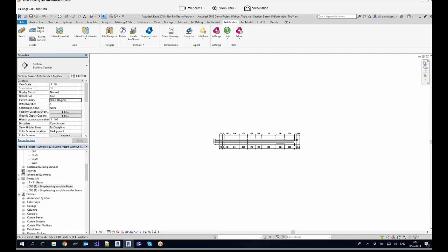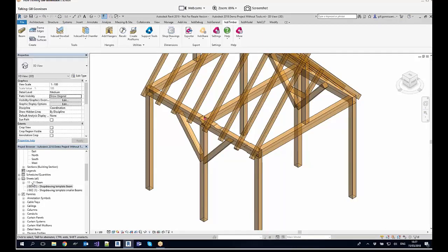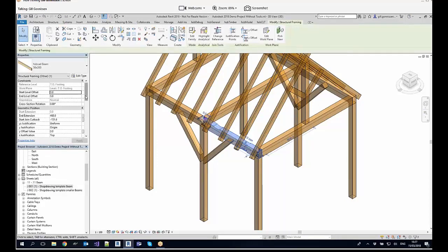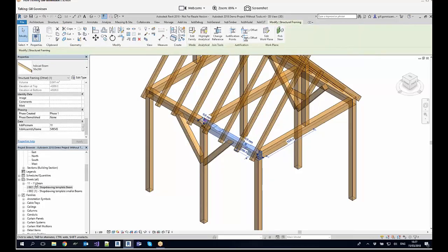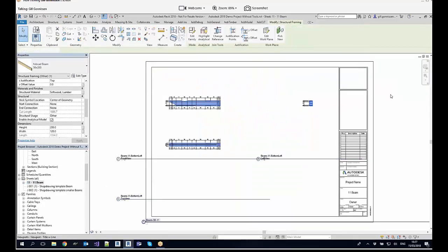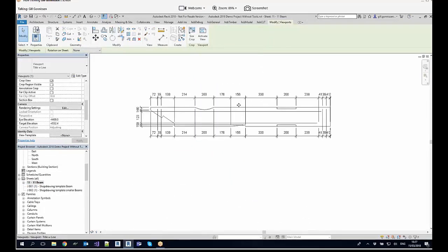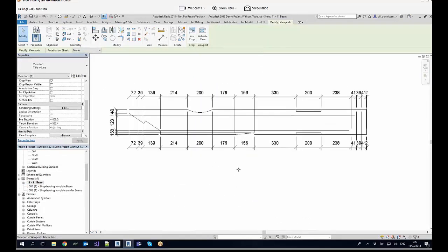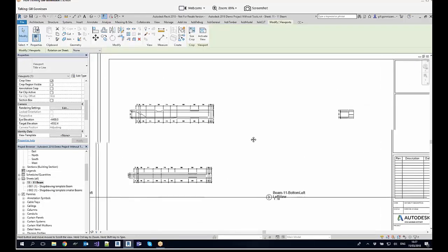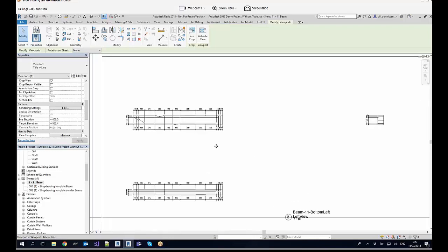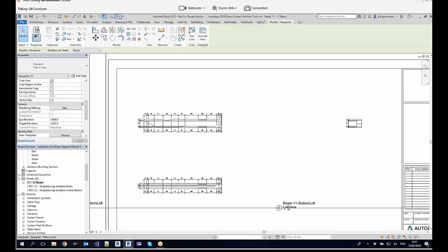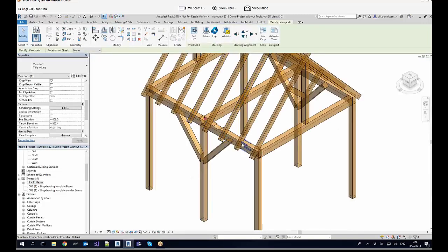And now it's creating the shop drawing with all the dimensions. Here we can see that the beam with Posnum 11 has been created. Here a sheet 11 beam. Okay, now it's selected. And we can see all the dimensions that are going on inside this beam. So here we have the chamfer, we have the arc, we have the shoulder, we have the scarf joint. So our shop drawings give us the correct dimensions. And the neat thing is that we can adjust, for example, the chamfer,